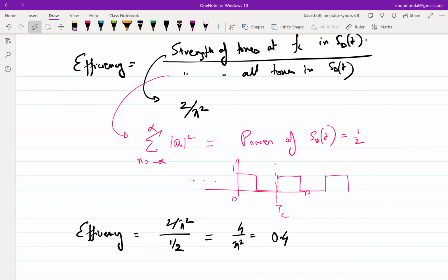Alternatively, if you are doing differential signaling, then you will have one input which is probably going from 0 to 1, the other will be from 0 to -1, or 0 to VDD, or 0 to minus VDD. If you're not comfortable with negative values, then you can say one is around some common mode, goes from 0 to VDD, and another goes from VDD to 0. So differentially, they become VDD to minus VDD. So logically, in terms of 1 and 0, they become 1 to -1. So in that way, the DC also goes off.